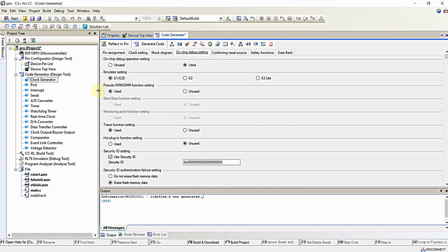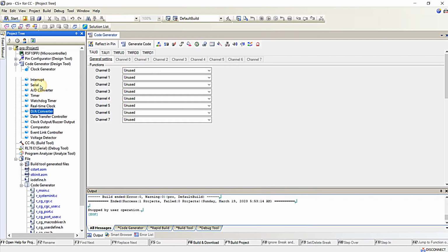That's it. These are all the required basic configurations that you want to do for almost all the programs. So now let's move on to configuring our microcontroller as per our application needs. Now that the basic configurations required for the microcontroller are complete, let us do the configuration required for generating pulses of required frequency and duty cycle with the help of the PWM module available in timers of this microcontroller. So before that,